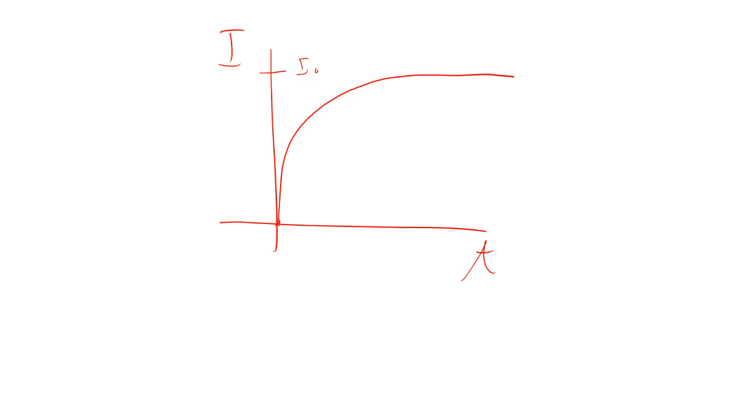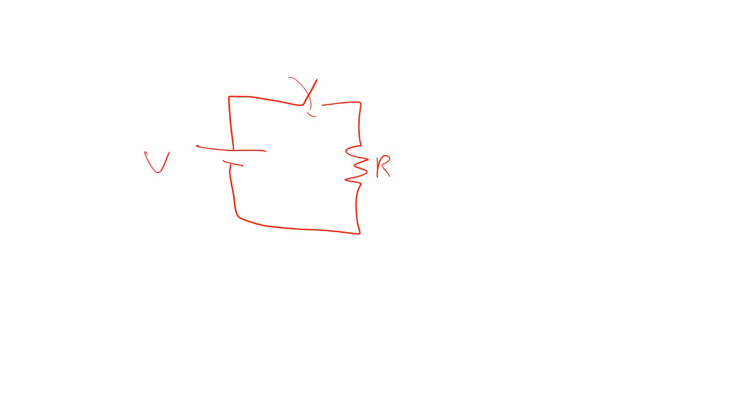In fact, if you had just any circuit whatsoever, even our simple circuit that we talked about a long time ago, with a V and an R, you close the switch and current starts flowing. Because current is flowing, you get a magnetic field in here. Because there's a magnetic field, you're changing the flux, and the change in flux induces an EMF that way. Even this tiny circuit would have a tiny bit of self-inductance.